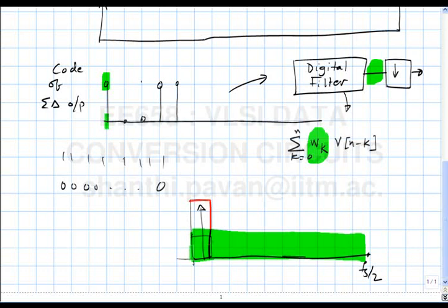Okay, let me ask you a question then. If I didn't do any low pass filtering and I downsampled it, what do you think will happen? Noise will all alias back. Yeah, and what will happen? It won't reduce anything. It will not increase by oversampling.